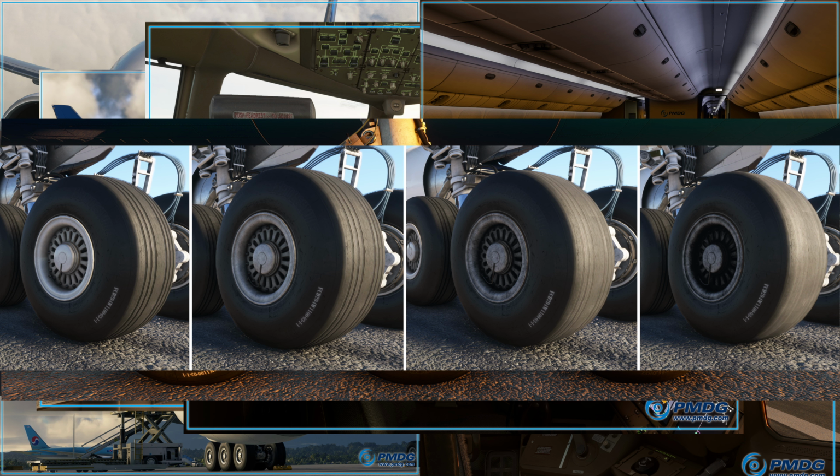Now, looking into the entirety of the system, during the walk-around you also have to check the brake wear indicator pins. Those are located on the inner part of the landing gear. I'm going to show you all of that in the upcoming tutorials. And they show the wear of the brake disc lining. Now, the further the brake wears down, the lesser brake action it will be able to apply if the brakes are really used to the maximum. Auto brakes really cover up for that stuff, but we'll have a little greater look into that when we can actually show you video previews.